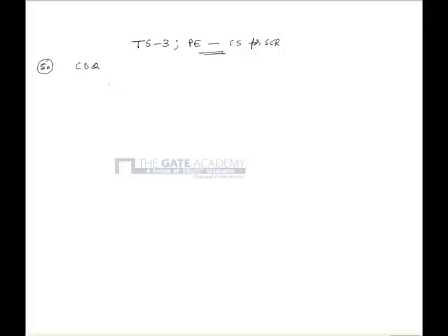As per the question, the resonant pulse commutation circuit of a thyristor T1 is as shown in the figure. The commutation circuit contains a capacitor C and inductor L and a diode D, and there is another auxiliary thyristor called TA, which is mainly for the commutation of T1, and the load which is shown draws a constant current of I0.